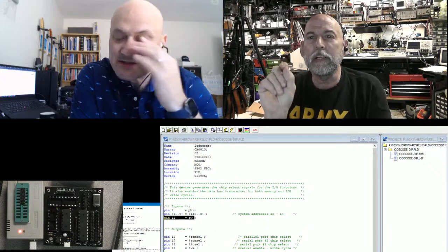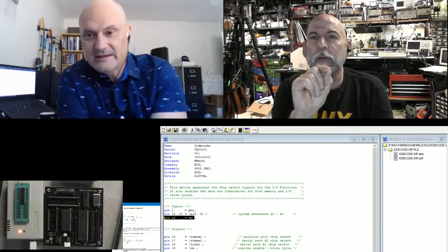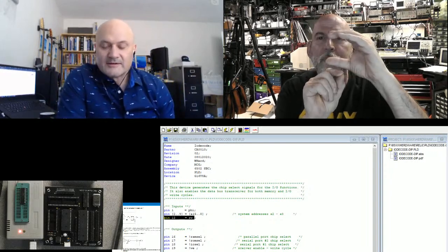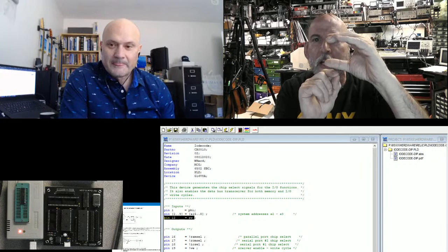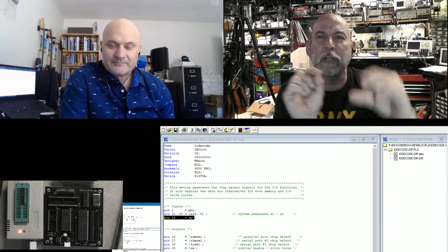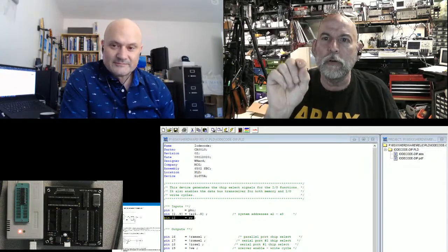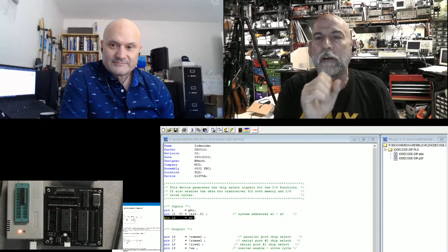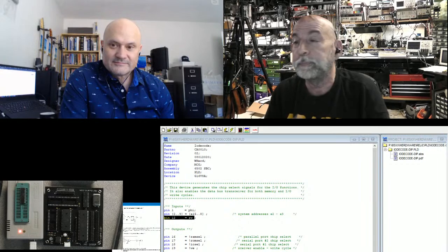Yeah. Now, at the end of the write strobe, the data is valid and has been valid for a period of time called the data setup, and it's held for a data hold time. So the strobe goes low when addresses are valid, and the strobe goes high when both addresses and data are valid on a write cycle. Yeah.